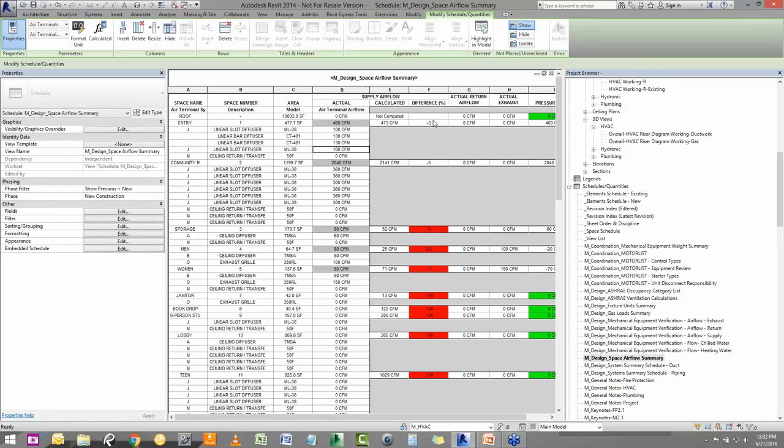Not horrible, but within my design range, because obviously we round up by 5 CFM or down by 5 CFM depending upon the application. 460 to 473, so I could wring out a little bit here. I could maybe make these 135 instead. Now I'm a little bit closer, maybe 1% of difference there. That's an acceptable answer for the HVAC industry, unless we're doing some really close stuff.